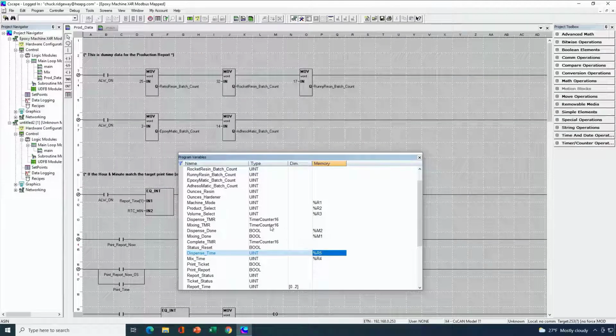Okay. And then from a Boolean standpoint, I really just have a couple of variables here that are mapped. Those are mapped into M's. And so if the outside device were to read 2 consecutive coils, then they could get all the data here as well. So that's really all there is to it. Very little configuration under hardware configuration, just mapping to appropriate locations for the variables you want to expose to the real world via Modbus, really, and you're done.